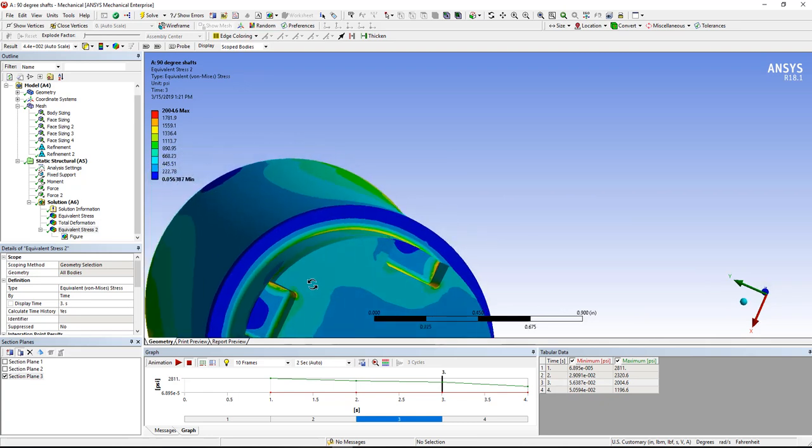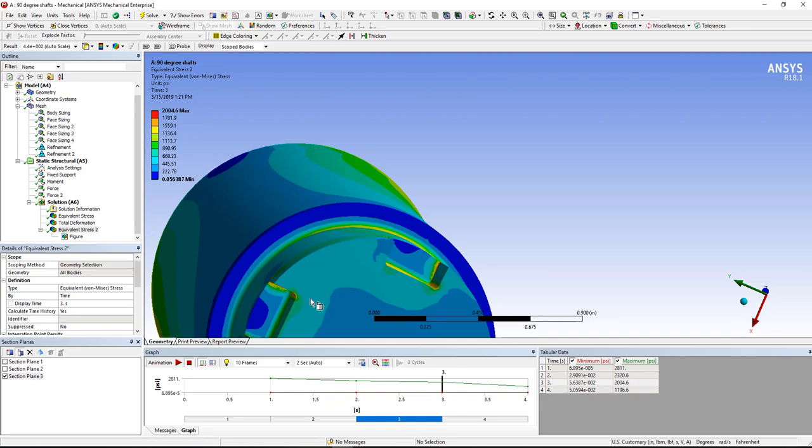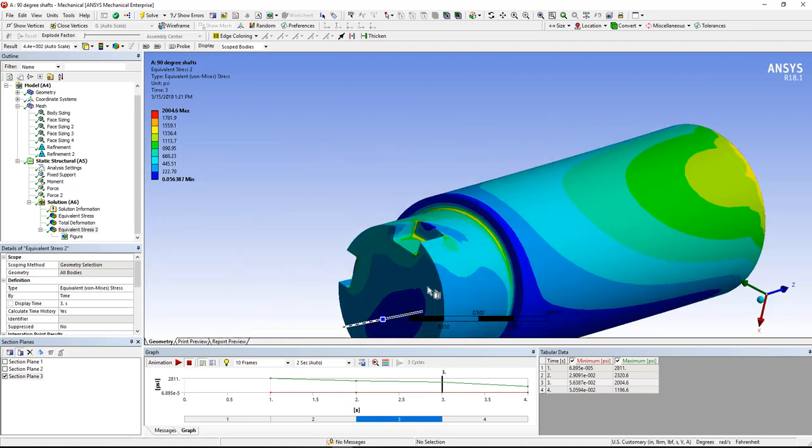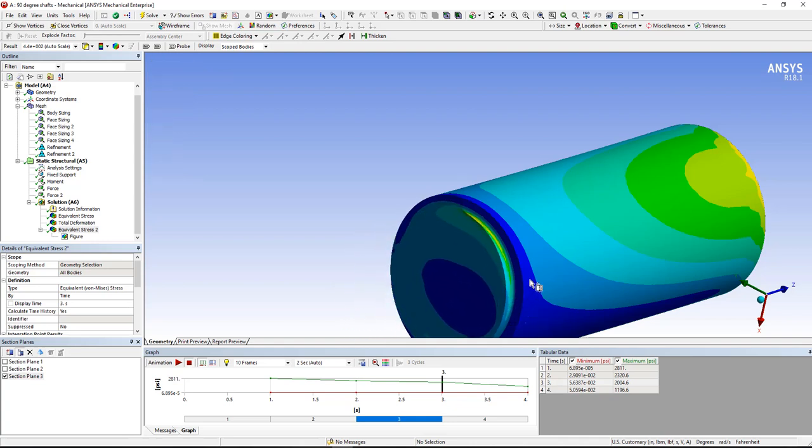Yeah, with the different meshes, it's hard to make a meaningful comparison between the two sides of this right now. But the other place to look at is in the fillet up here. What's happening down below. You can see some effects because this isn't square on the shaft, because it's just a hand-drawn value.